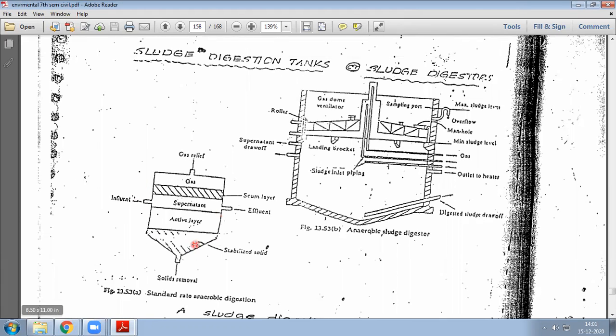So it's a tank made up of concrete. So sludge will be deposited here. So what happens when it comes? It will mix with the already existing content or any sludge that is there. Okay. So you all know after certain times gases and all will be released in any wastewater. So the main gases released here are methane gas and carbon dioxide. So methane, in villages, is used as biofuel or for cooking purposes.